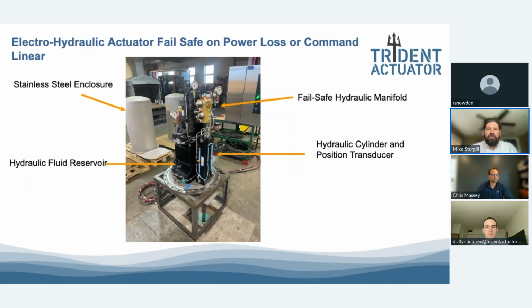And just so you have an idea there, we use 3/16 metal tubing because that hydraulic pressure can be up to 3,000 psi. We're usually around 2,500. And just so everyone knows, we don't keep these gauges on there. They are capped off once we put the enclosure on. We just do this for testing in our factory.